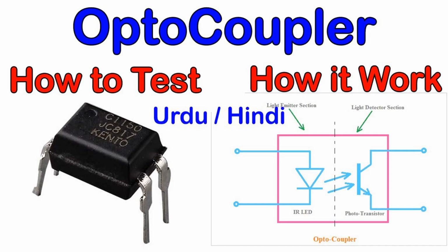Here are some key aspects of signal conditioning. Amplification. One of the most common signal conditioning tasks is amplification. When a weak or low-level signal needs to be boosted to a usable level for processing or measurement, an amplifier circuit is used to increase its amplitude. This can be achieved with operational amplifiers, op-amps, or specialized amplifiers designed for specific purposes.